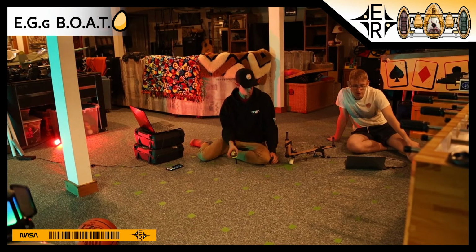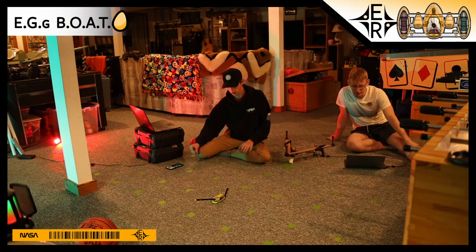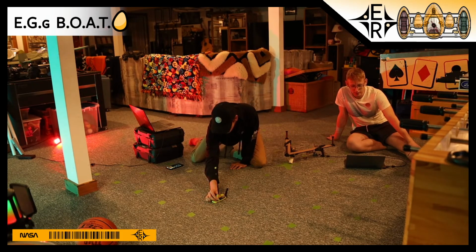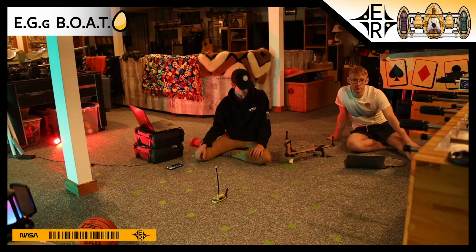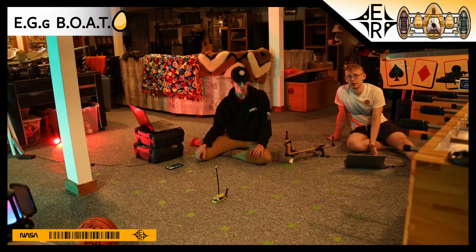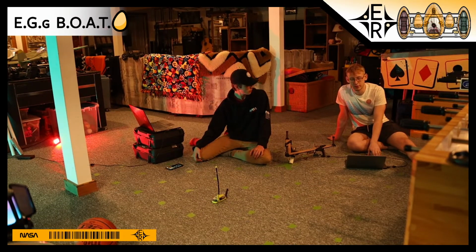So yeah, we're reading the 4 output channels right now. It seems that when the antennas aren't receiving anything, the outputs are 658, 10, 10, 658. These are values on a scale of 0 to 1023, where 0 represents 0 volts and 1023 is 5 volts.